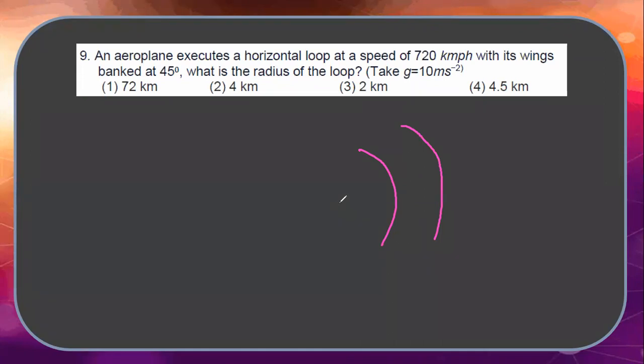Then necessary centripetal force they'll get. What happens? Outer wheels they'll rise up. Accordingly, road or the track should be raised. That we call angle of banking. How much that angle is to be raised, that depends upon the radius of the circular path. Fine. What did they give?